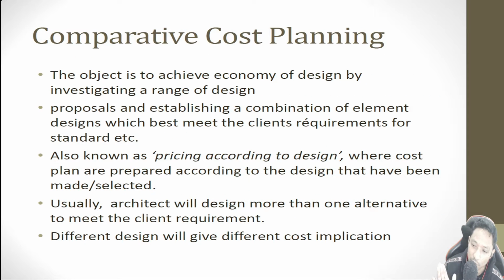So moving to the next method, what is comparative cost planning? The objective is to achieve economy of design by investigating a range of design proposals and establishing a combination of element designs which best meet the client's requirements for standard, etc. Also known as pricing according to design, where cost plans are prepared according to designs that have been made or